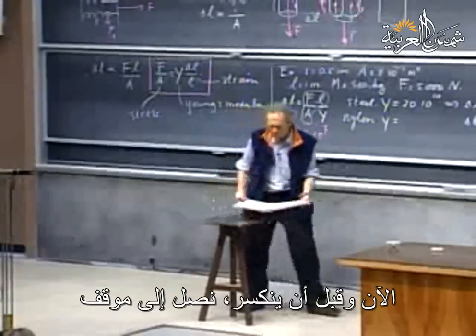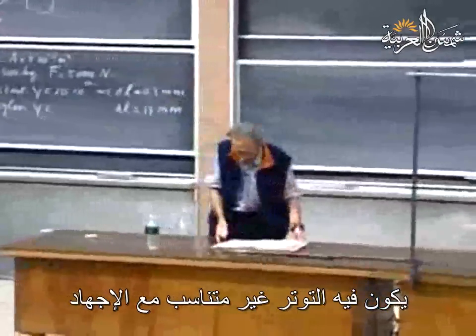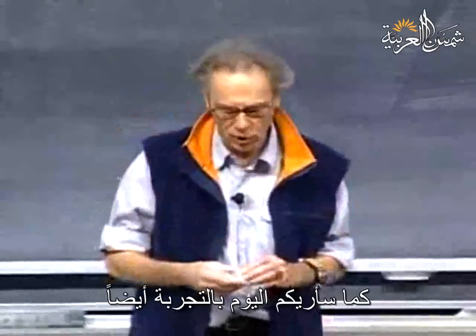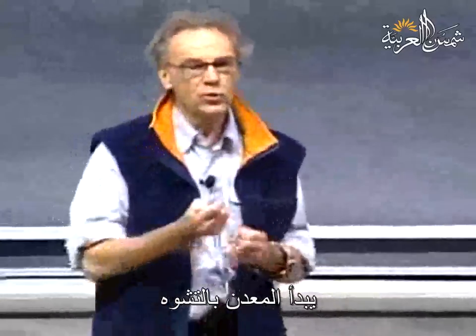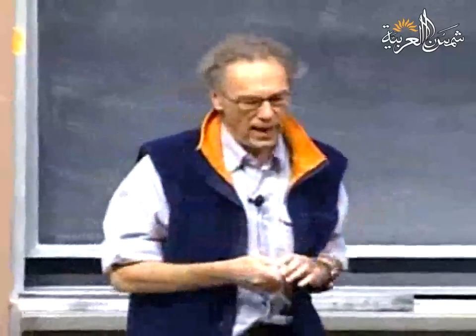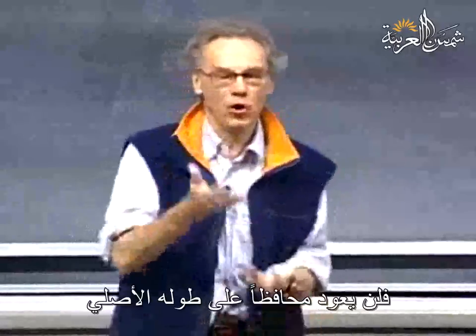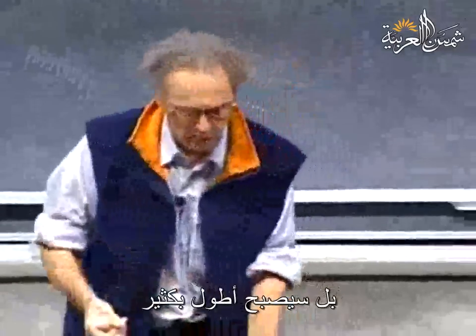Now, before it breaks, we reach a situation that the strain is no longer proportional to the stress. In other words, we abandon Hooke's law, as I will show you also today with a demonstration. The material begins to deform. It begins to flow in a way. And when you take the weights off, it will no longer have its original length. It will not return to the original length, but it will be much longer.